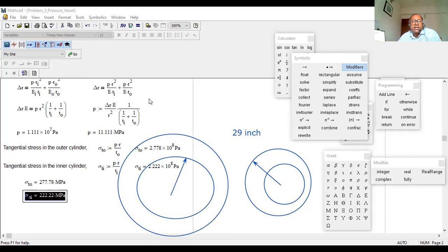Yes, sir. So instead, say this one has 28.79, just for example, inch. Can you put it? No, sir. What options do you have? Heat the outer cylinder, and when its diameter increases, then you can put it in. Then wait, let them cool down. After cooling down, it comes back to room temperature. Say after heating, this diameter becomes 29.01. Then easily it will enter the inner one, right?